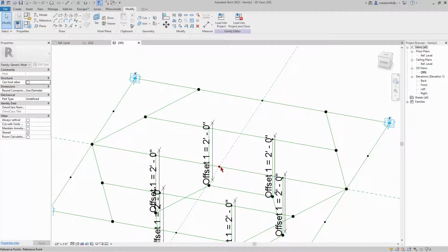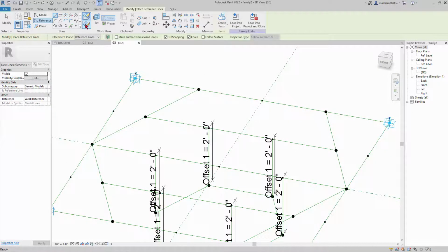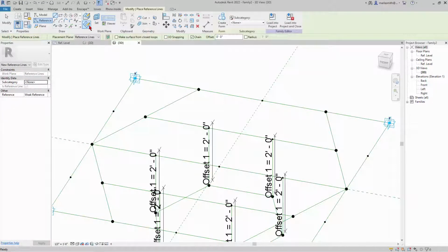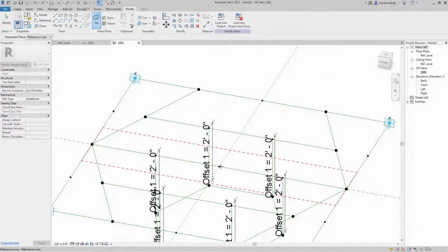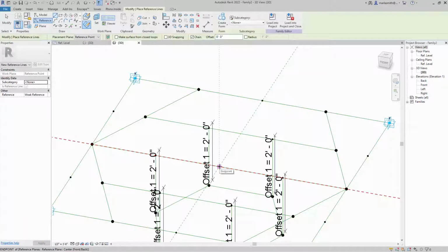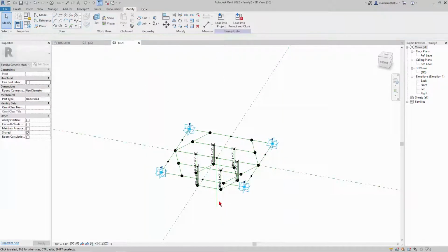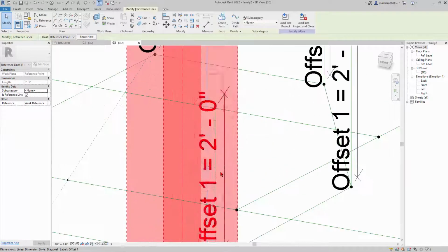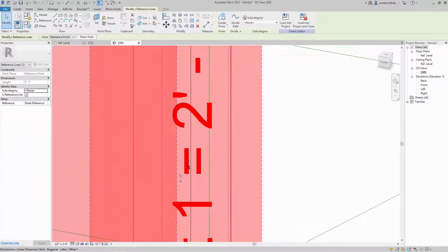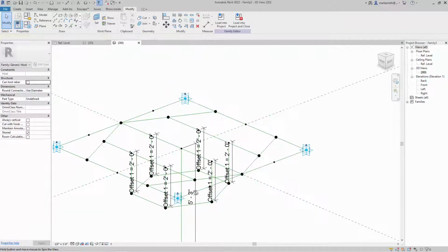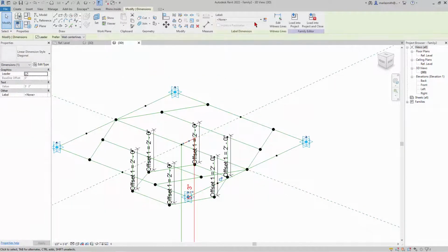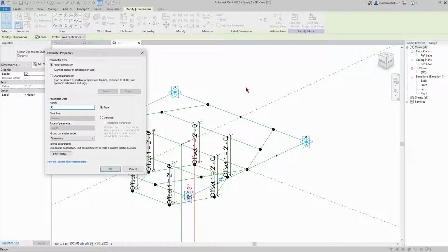So that happens on this guy. I'm just going to go to Reference, Line, set it to Draw on Face, get rid of 3D snapping, sorry, and go back to Draw on Work Plane. And I'll set this guy to that point and draw a line directly down, and do the same thing. So I'll pick that, kind of zoom in, make that permanent. There it is. And then I'll make a new parameter for that, and I'll call that offset 2.